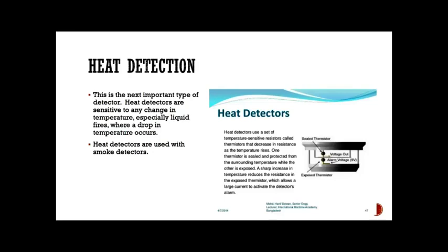You can see it's sealed and protected from the surrounding temperatures while the other is exposed. A sharp increase in temperature reduces the resistance in the exposed thermistor, which allows a large current to activate the detector's alarm. So a lot of times you will find, especially in commercial buildings, that this will be required.